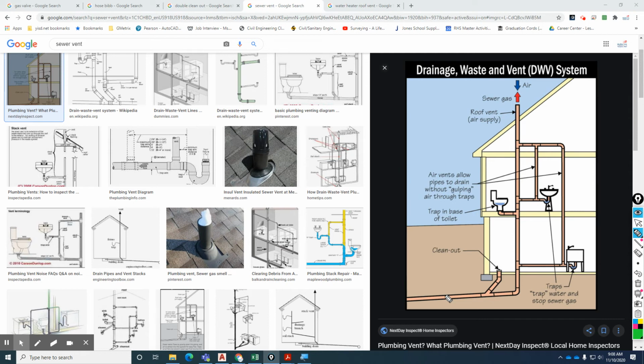Sewer systems, water systems are actually civil engineering, and that's a specialty. Just like Nancy mentioned, that's all she specializes in. And you can kind of see, because they have to calculate slopes and how much it carries. They need to talk about peak flows. When do you use a sewer line the most? Usually, sewers are used mostly between 6 and 9 a.m. in the mornings. What's happening during those times?